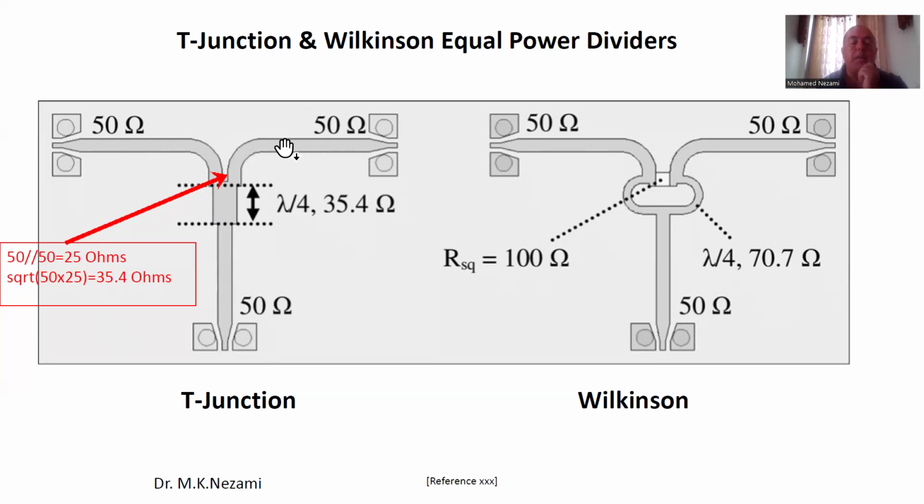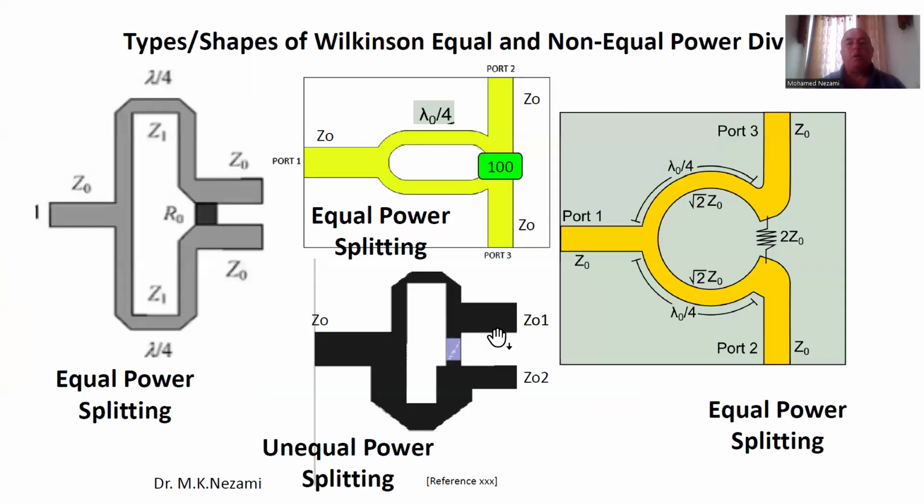So therefore, for the return loss of this, as I will show in a minute, the most you can have is 6 dB on these two. Versus here, it depends on your design, so you can have 15 dB or better on the design of these. So now the Wilkinson divider also, we're going to cover more of the Wilkinson divider in another lecture within this series for antenna feed networks.